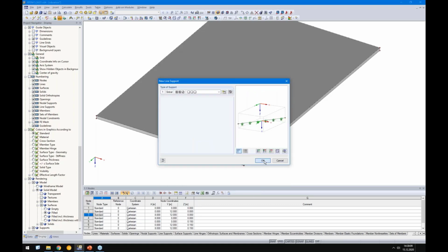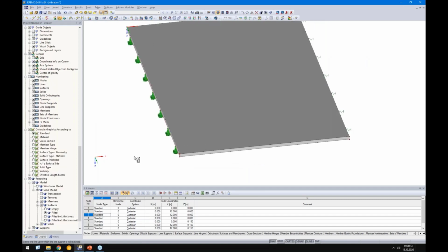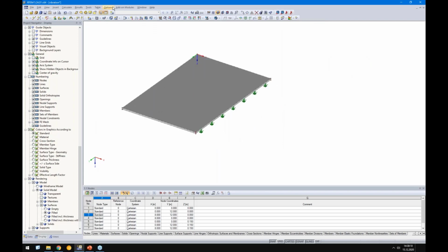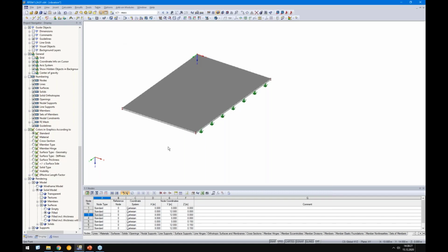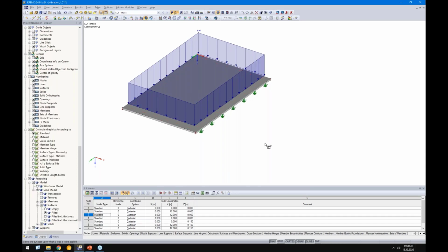Okay. So this line and this line. Okay, I will add a load case. So load case 1, that should be the mass. The self-weight is already included in this 595 kilogram per square meters. So I define here directly the force of 5.95 kilonewton per square meters.